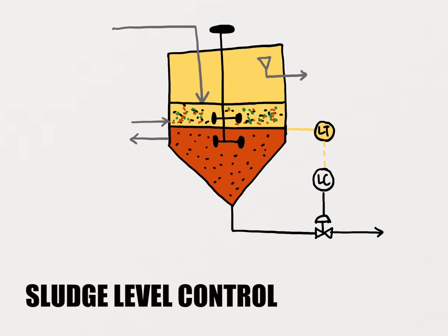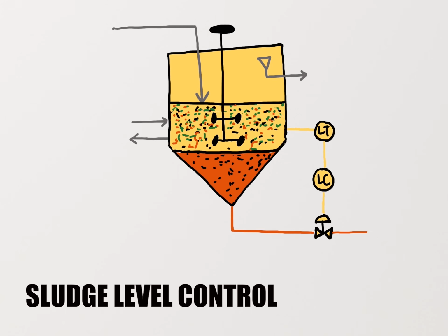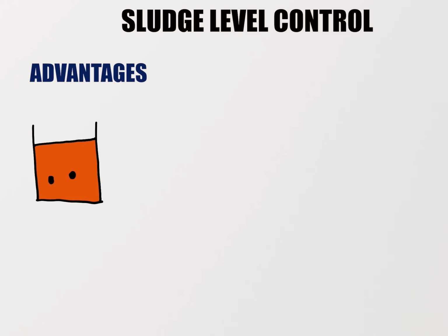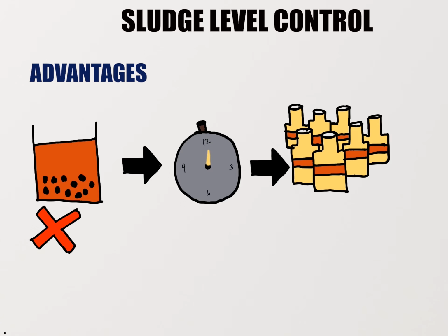The level control will compare the measured value with the set point. The controller will transmit the signal to the control valve of the sludge to manipulate the outlet flow rate of sludge. High concentration of particles in the tank will prevent the particles from settling. Hence, this control system is able to reduce the residence time needed and therefore increase the production capacity.